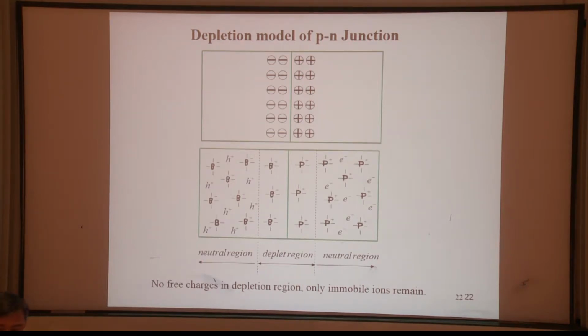All right? This equilibrium will be formed because diffusion actually causes current. So when we put the p-n junction in contact together, there will be a transient current occurring at the time when we contact them together. But this current will not be produced continuously. All right? We don't have these good things. If this did happen, then we would have electricity always. So this will not happen. Just transient, for a very short period of time. Eventually, they will become equilibrium. The equilibrium is caused by the built-in field at the interface that exerts a force against the diffusion.